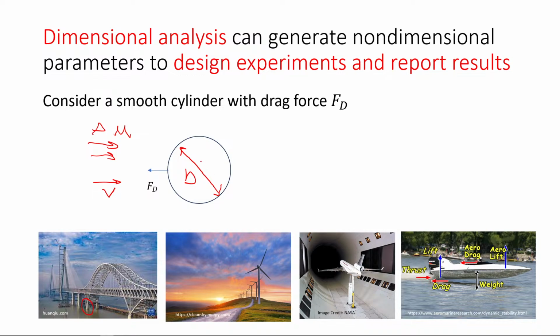This diameter here would be smaller than this one. You need to achieve kinematic similarity, which has to do with the velocity, and you need to achieve dynamic similarity, which has to do mainly with the forces, and forces have to do with mass, which depends on the density, for example.